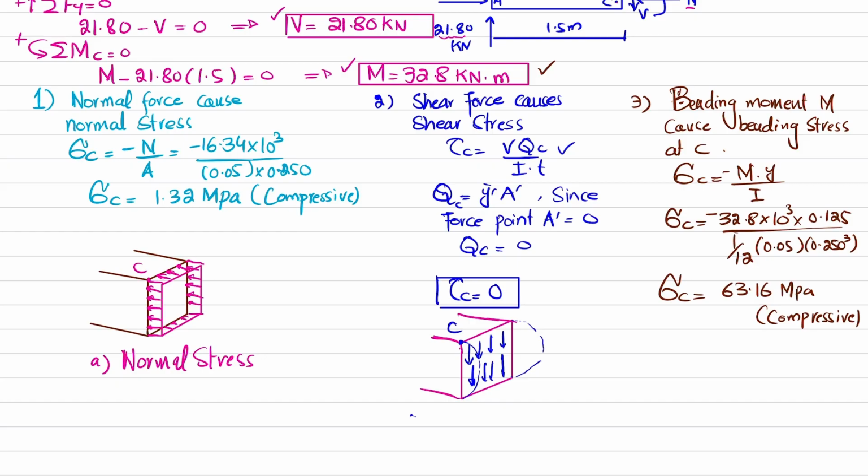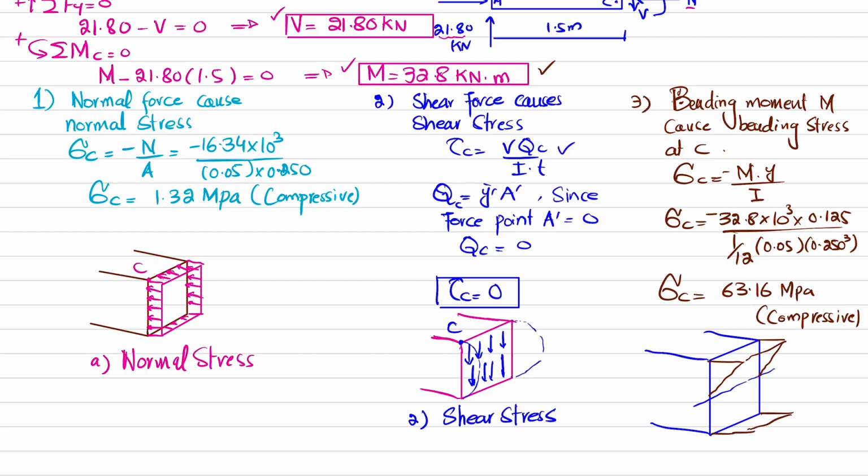So this second case is about shear stress distribution in this rectangular section. And the third case is for the bending stress. So how we will do it, this is its neutral axis. Here, this is the beam. And we know that the above one was in compression. So I can write it like this. This will be the diagram. And below one is in tension. I will also show you how it will be in tension and compression.